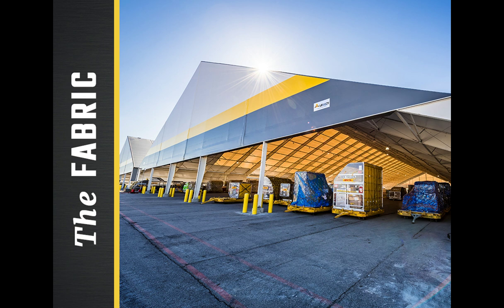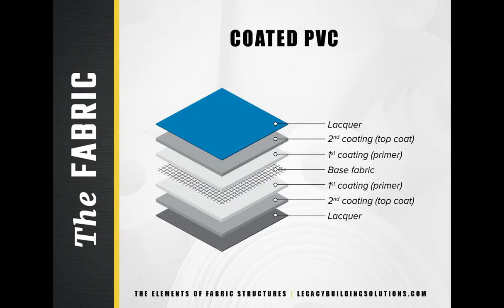In a fabric structure, fabric is attached to the frame via a keder rail. Though the fabric is a redundant brace to the frame's outer flange, it is not included when designing the frame. The purlins are the lateral support the rigid frame anticipates in the design process. Additionally, cables and steel rods are attached to the frame to transfer longitudinal wind forces through the roof and into the walls, eventually terminating in the foundation.